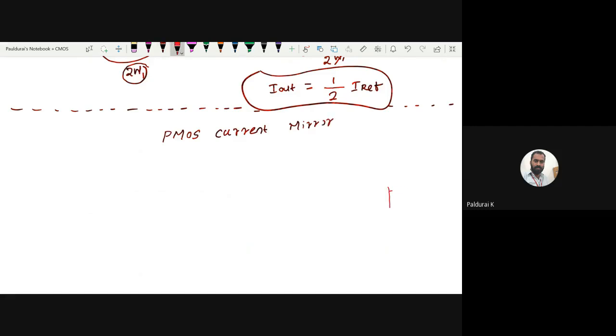See, here I am having some reference current, right? The logic is very important. The reference current, here I have a current source. The NMOS will simply act as a current source. Now I want to copy this current here. This I out should be equal to I reference. For that, what we learned is to connect a diode-connected device. You inject this current into the diode-connected device. Now it will generate a voltage, feed this voltage to the current source.